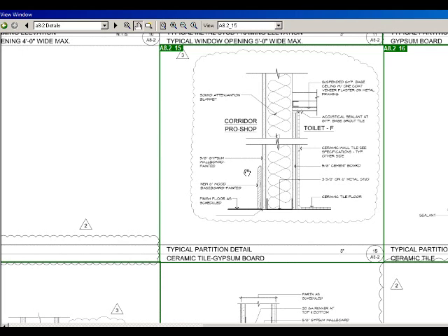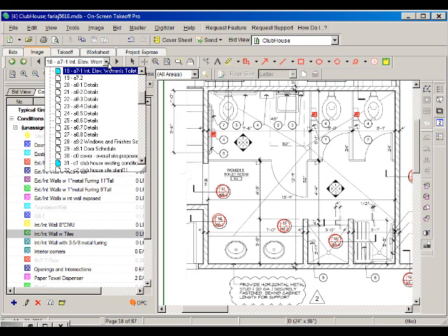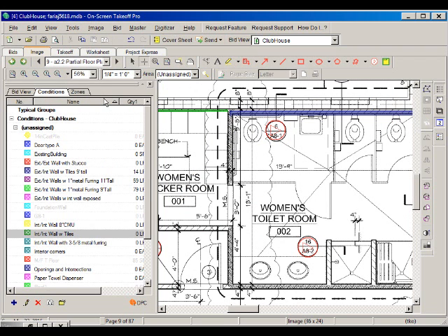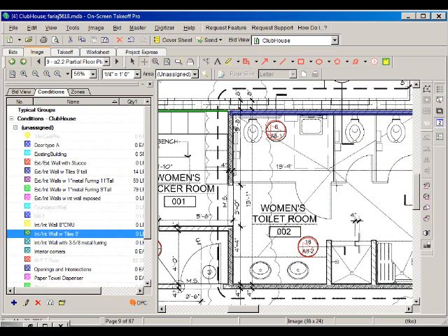We have the 5/8 cement board with insulation and tiles on one side. So this is going to be an interior wall with tiles. This one here, that's what we're going to be using, and the height for this wall is going to be 9 feet. So I can type in here, this is going to be 9 feet. Click OK, and then basically we will follow just this direction here, and that's the wall that we are estimating.